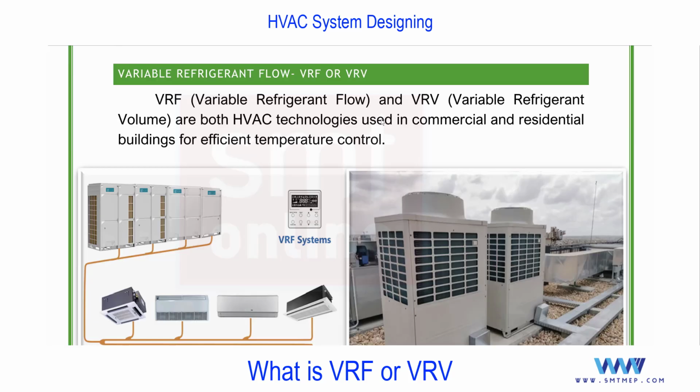What exactly is DX? I'll give you the idea after this topic. At this level, remember DX system means the refrigerant is responsible to cool the air, compared with the chilled water system. So VRF also comes under DX system. And in VRF, if you compare it with the split system, the major difference is that in a split AC or ductable split, you can connect one indoor to one outdoor. But in case of VRF or VRV, we have the option to connect multiple indoors to one outdoor.